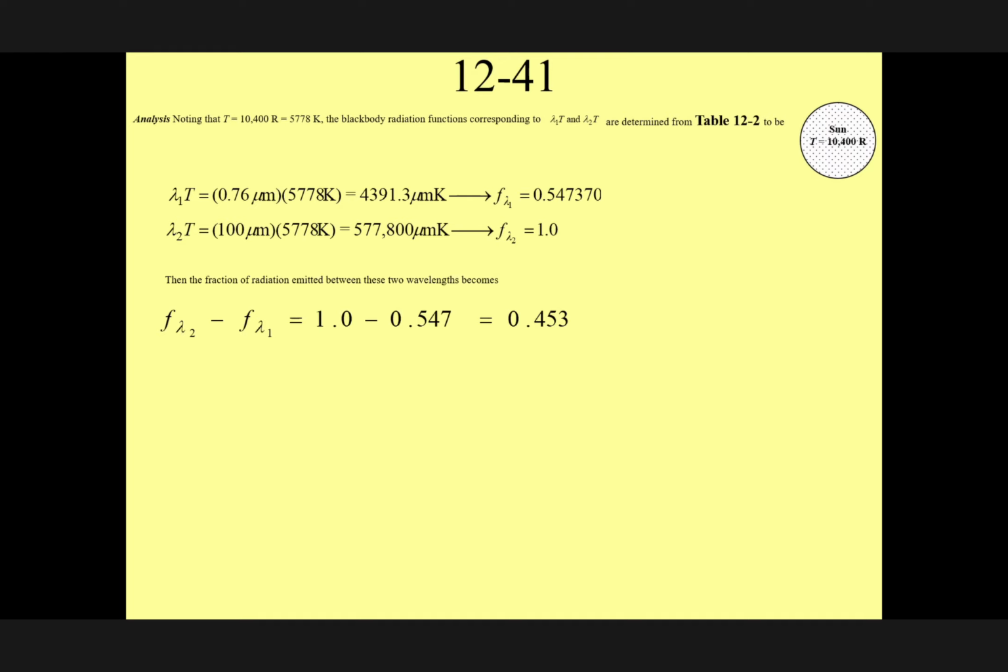How do you calculate the total energy now? If you would like to calculate in watts per square meter, how much energy it is? We multiply by the temperature to the 4 and the sigma. Sigma, yes. That's right. As I mentioned, this is the percentage. That represents that percentage over the total. The total is sigma T to the power 4. Therefore, we can calculate how much energy. Okay. Now, let's look at this next one.